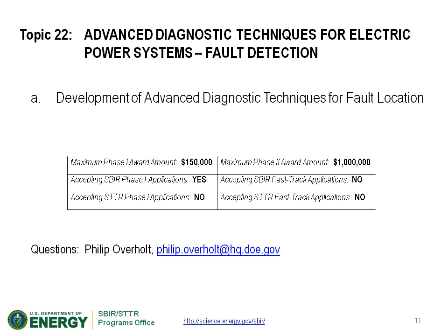So with the other features, you should be able to record what you're measuring with a partial discharge, and transmit that information back to a location that could take some action. This should be able to be deployed over a wide area on a transmission or distribution system, so that you have a large coverage over that area.